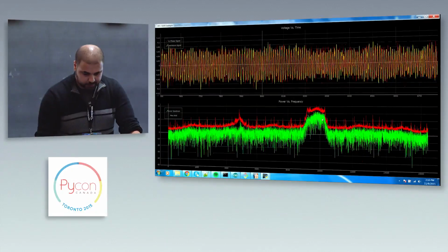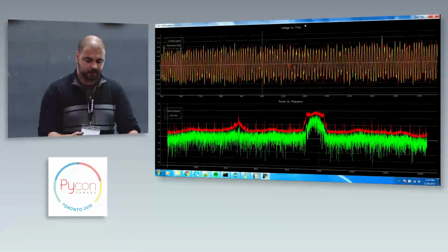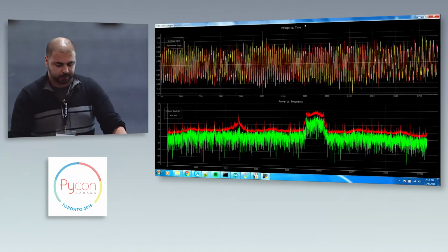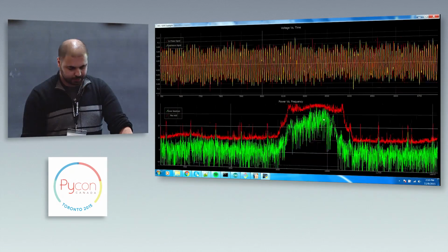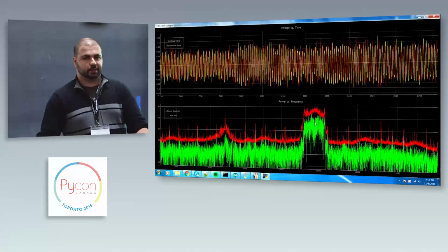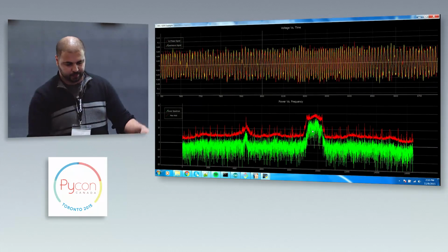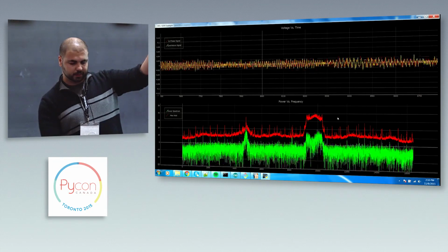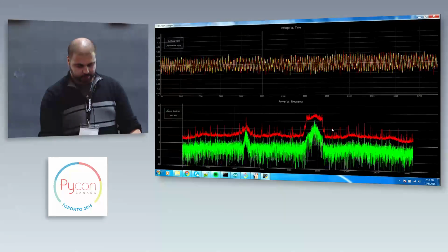And at the bottom is the power spectrum versus the frequency domain. So I applied some IQ correction, and then the FFT, 20 log of the FFT. And that's what that wideband signal is. It's not really that wide. It looks wide because the sampling rate is so small on this thing. It looks really wide, but it's actually not. So if I actually move this up, I'm hoping I get something more, but it doesn't look like it. It actually went lower. It's a little bit better down here.